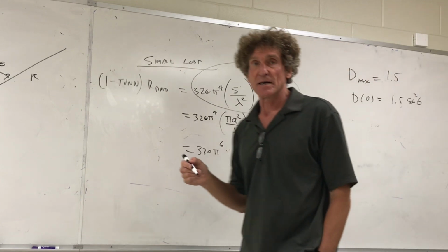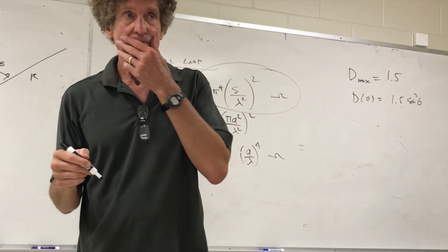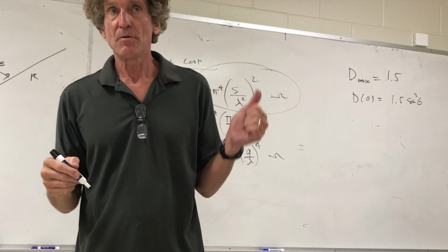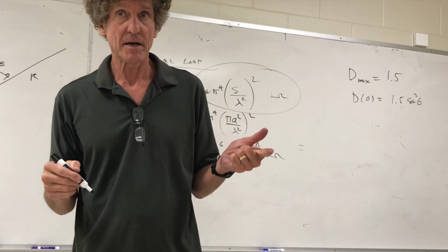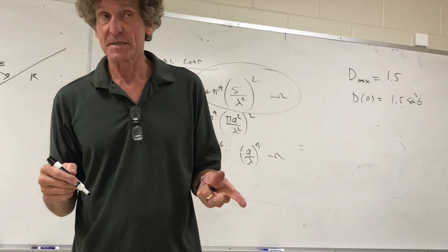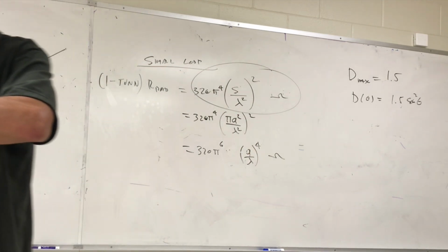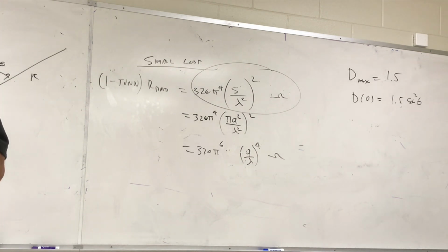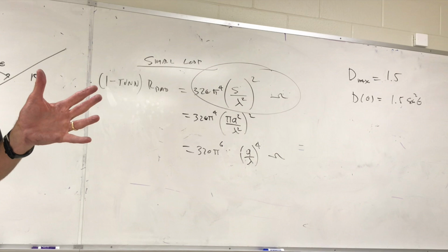Now that's really nice. With me? All right, so that's the short dipole, the arbitrarily long dipole, and the field pattern we got. Then a half-wave dipole, exact half-wave, then a half-wave cut down to 0.485 lambda, right? We got the field pattern, the directivity, the radiation resistance, got everything of interest, right?